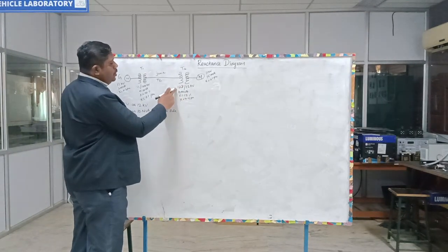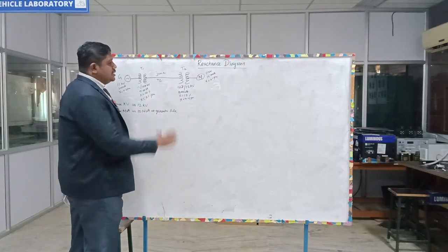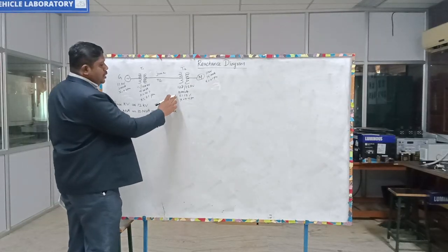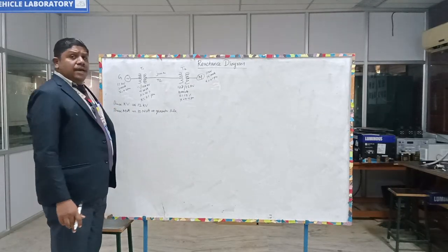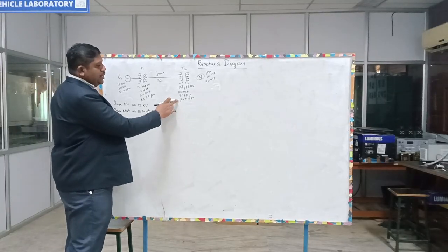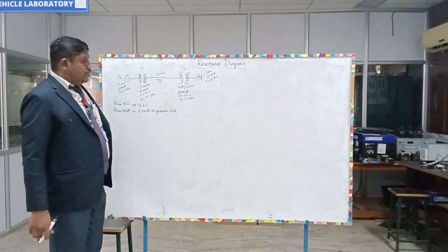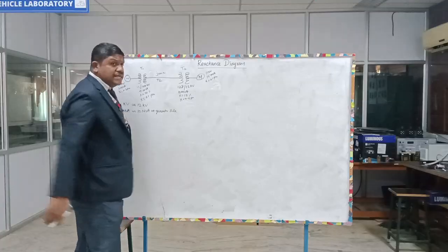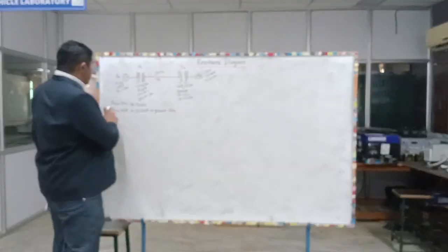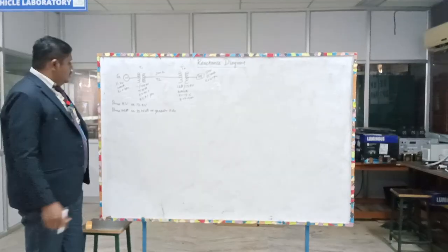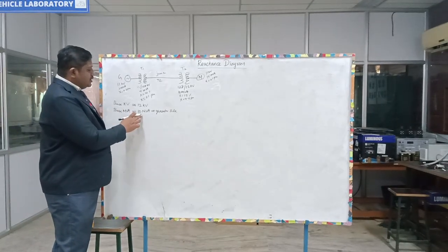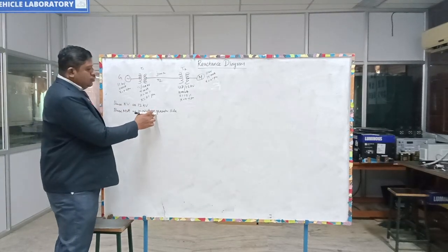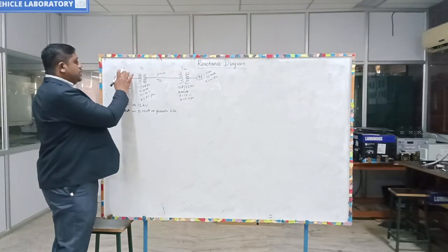Then T2 is 128 by 12 kV. It's a step-down transformer, with a 10 MVA rating. The reactance is 15%, so in terms of per unit, X is equal to 0.15 per unit. Then we have the motor load 11 kV, 15 MVA, and X as 0.1 per unit. So we have the base MVA. It's given in the problem as base MVA of 10 MVA and base kV as 12 kilovolt, and assume it is on the generator side. So the generator side is over here.